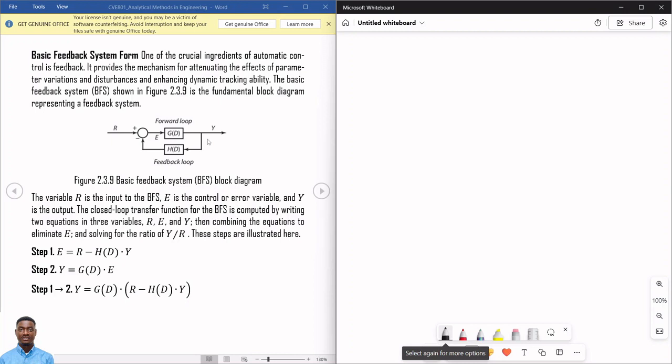Once the set point in the room is already attained, then what should happen is that the air conditioning system should stop cooling the room. That automatic control can only be made possible if there's a feedback between what the sensor is measuring as the temperature in that room against what the AC system is doing. So that is when you have a feedback system.